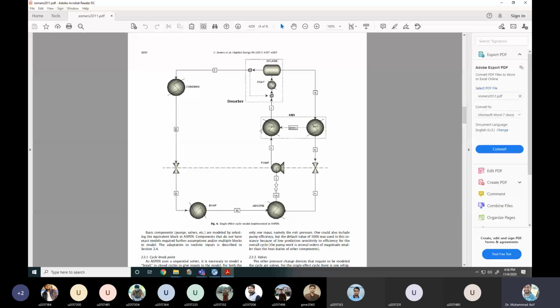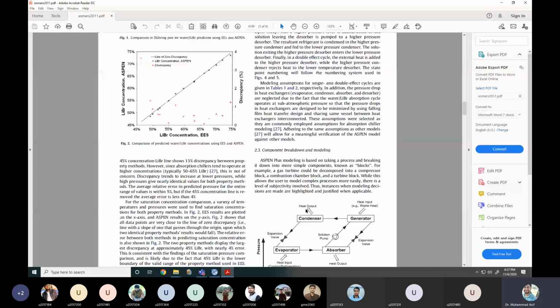So there is a heat exchanger, right? This is just to increase the efficiency because this is a concentrated solution. So we want the lean solution preheated. This is preheating before entering into the generator. Similarly, this is pre-cooling before entering into the absorber, because in the absorber we want low temperature. So this is pre-cooling, this is preheating. This is the heat received by that, so this temperature will be decreased. Similarly, the cold temperature will be increased. So this process is the same as this one, right?